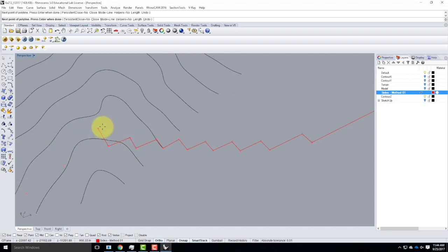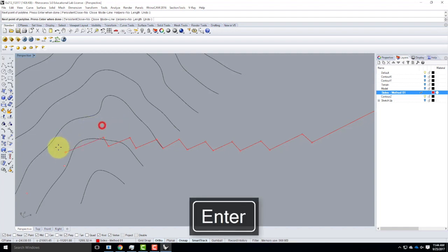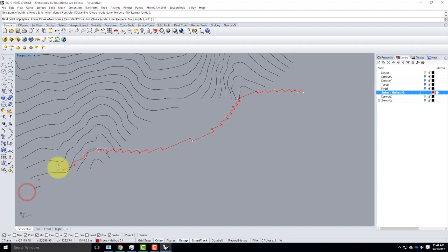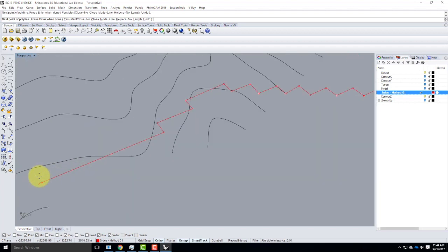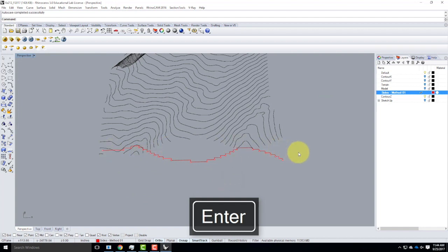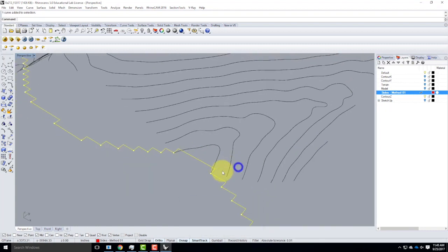This is the bottom of the valley, 39.063 feet. Straight over. And we're just going to end right at that point, which was my last line. So now I'll take all of those points, so SELPT, select point, plus the line, and I'm going to rotate them back. I rotated right around that point, so I'll rotate